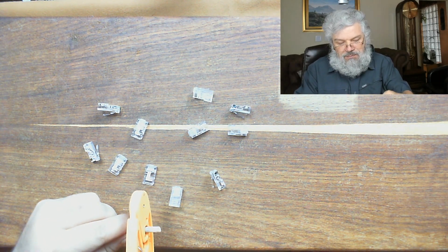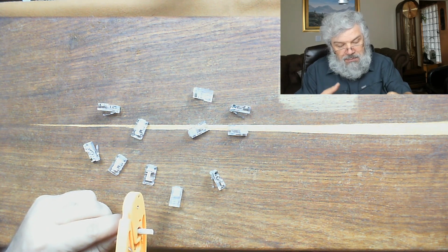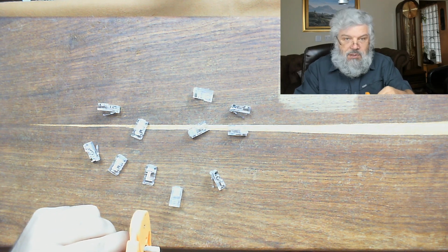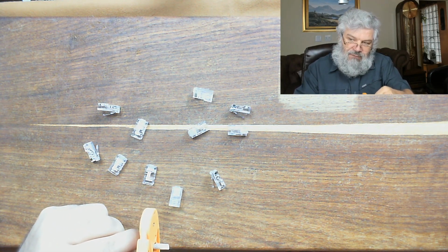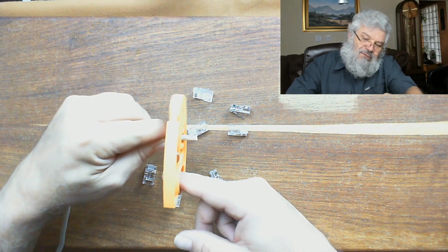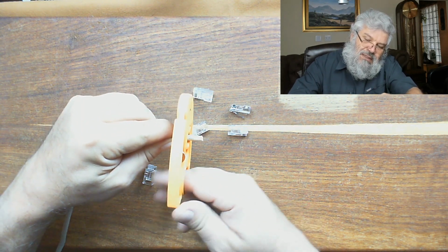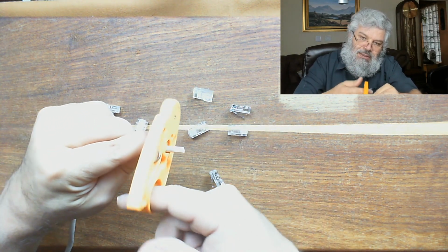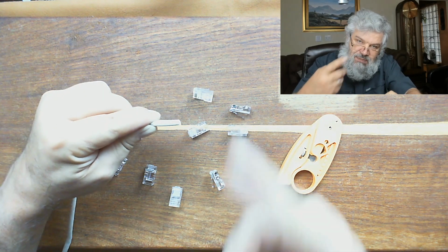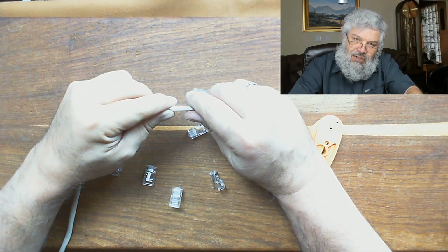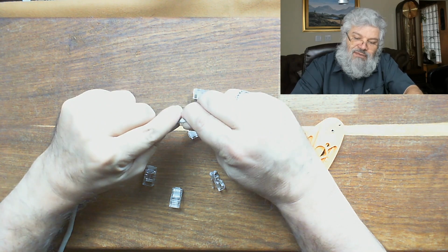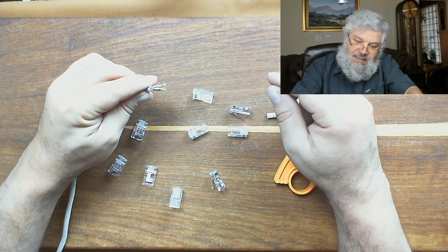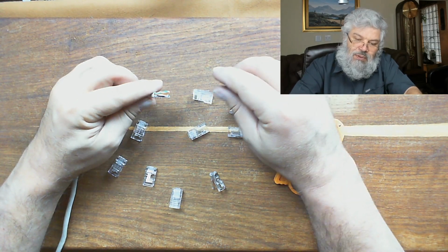If you've got a professional stripper like this, it makes life a lot easier than trying to do it with a penknife. One word of warning: you simply insert the wire, but if you cut it, make one turn. If you keep on spinning it, then chances are that you will cut one of the wires on the inside, and you don't want to do that, because if the wire is cut, then the connection will not work.